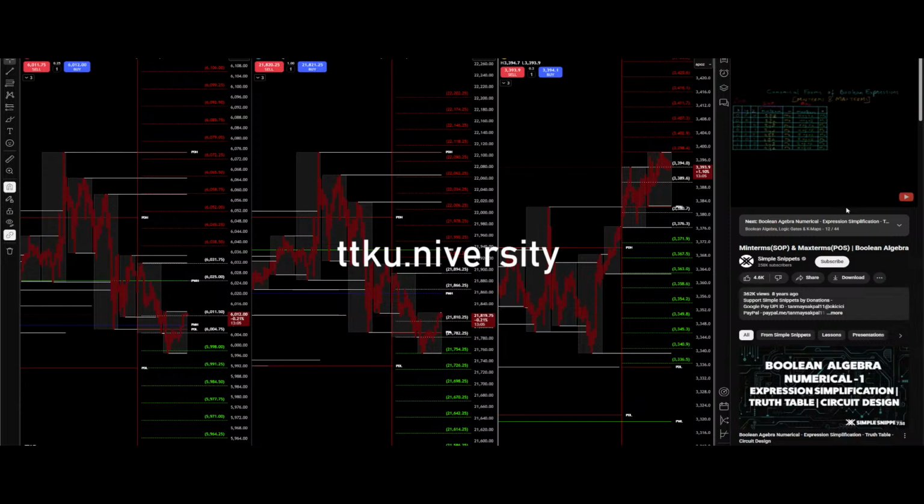So why did I write them like that? Since the initial values of x, y and z for this column are 0, we need to convert them to 1 so that the product ultimately results in 1. Now when we take an AND operation between x, y and z, the only case where the value is 1 is when all these variables are 1. So since all these variables are 0, 0, 0, we take their complements, which ultimately gives us the value 1.